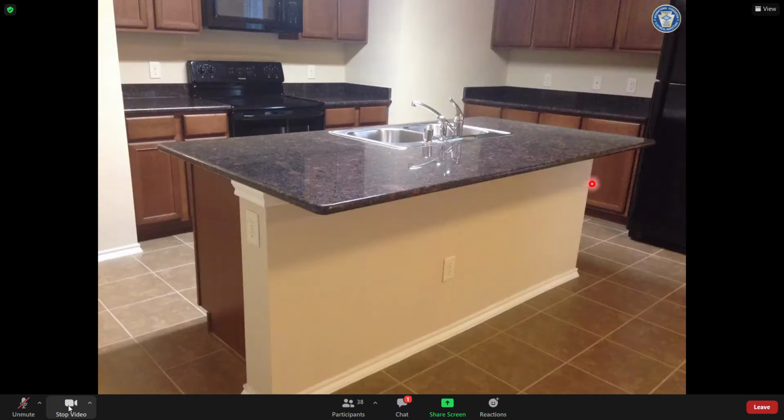Under the 2017 code 2018 IRC, what am I going to do? I'm going to take a measurement right there first and see if that's less than 12, which it looks like it's not. Then I'm going to take a measurement this way and that way. And if I come up with 24 inches or greater this way, 12 inches or greater this way, then that means I have to have a receptacle to serve this countertop. And there it is, under less than a 6-inch overhang.